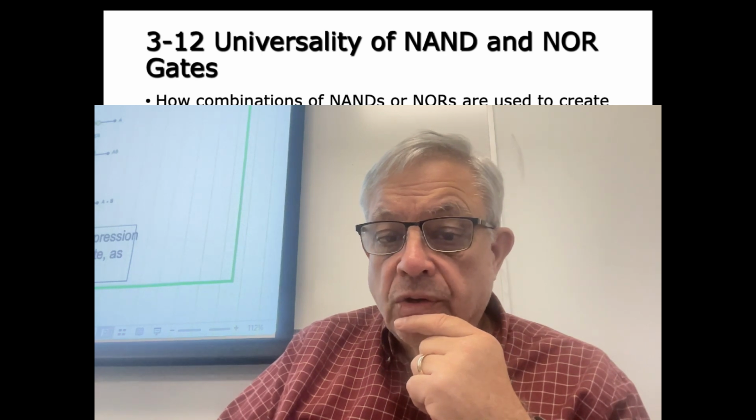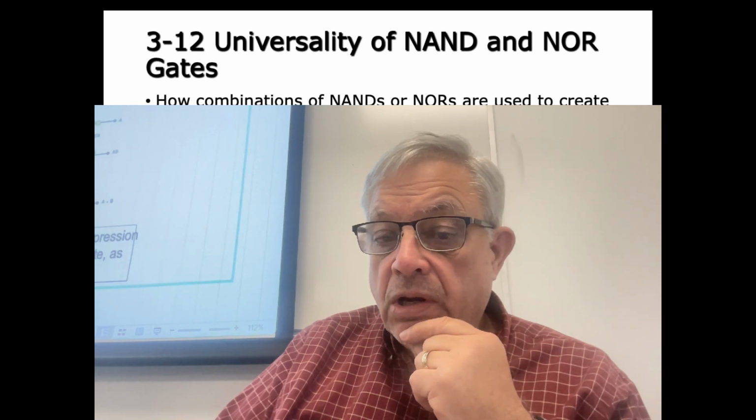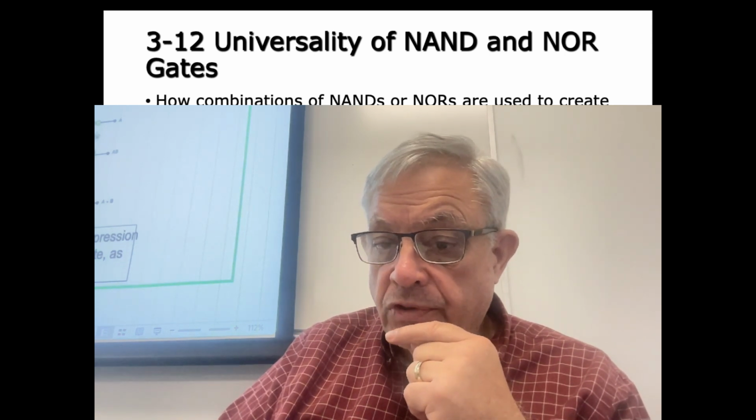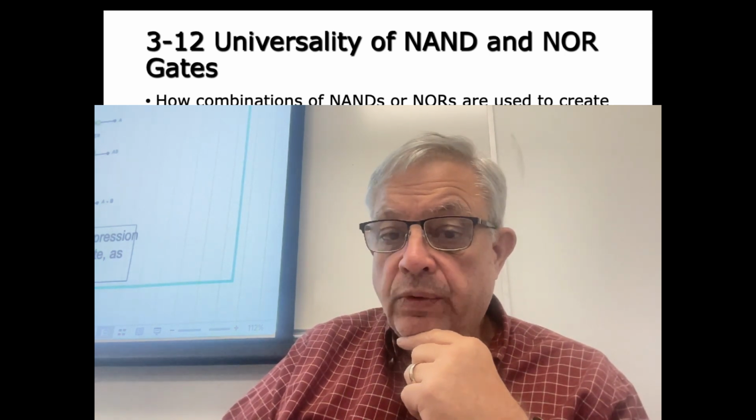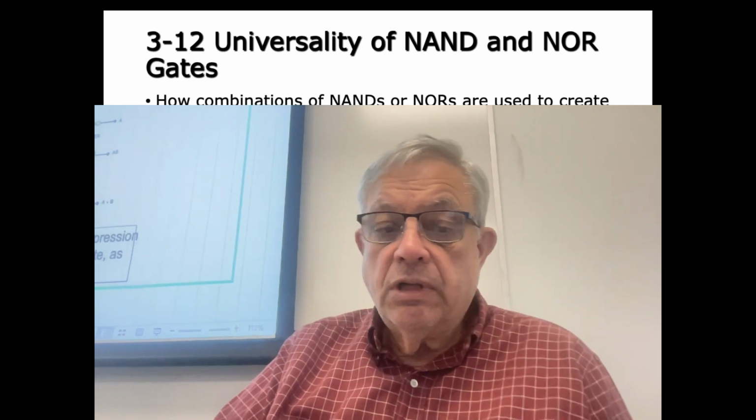We can take a single chip and tie both inputs to the same source, invert, and we've got the inverter. So we've got the inverter, we've got the AND gate, we've got the OR gate using just NAND gates.